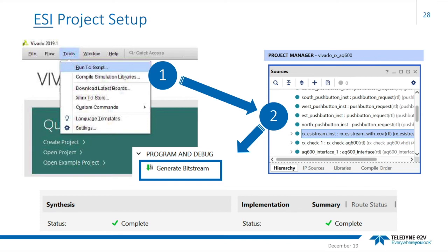The final stage is to load the bitstream to the target FPGA using the hardware manager. From here, the TCL file can be modified and resimulated just like any other Vivado project. Once satisfied with the current project, the IP code generated can then be downloaded to the target FPGA using the hardware manager.